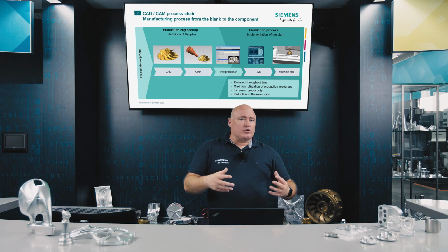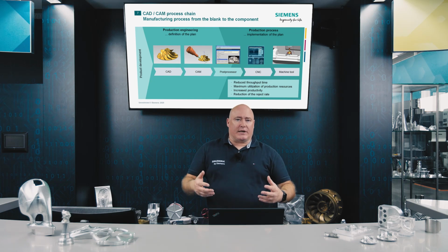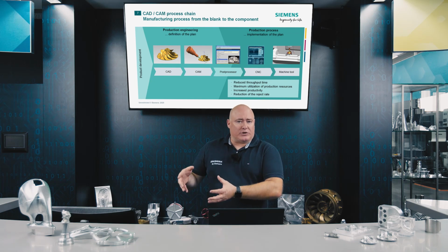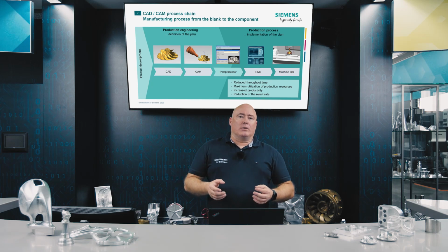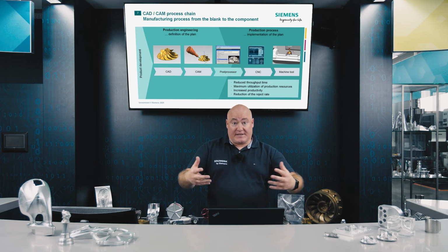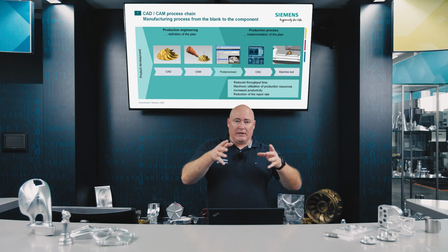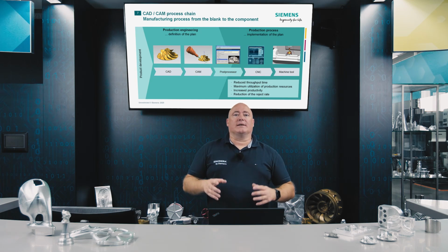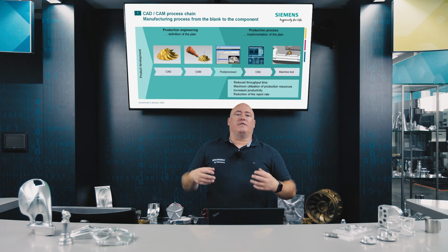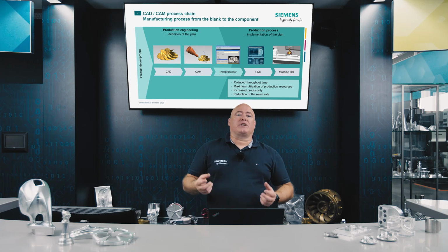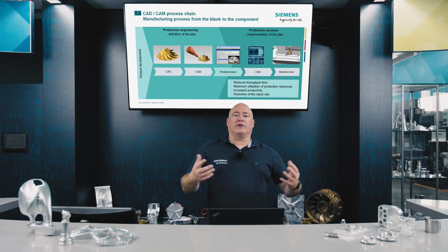Because a single part can be produced just as well via a CAD/CAM process chain as a component for mass production. And mold and die making, especially in mold making, just doesn't work without the CAD/CAM process chain because many molds and geometries are too complicated to enter into the control system manually. It's mathematically impossible and not feasible in terms of the sheer volume of data.